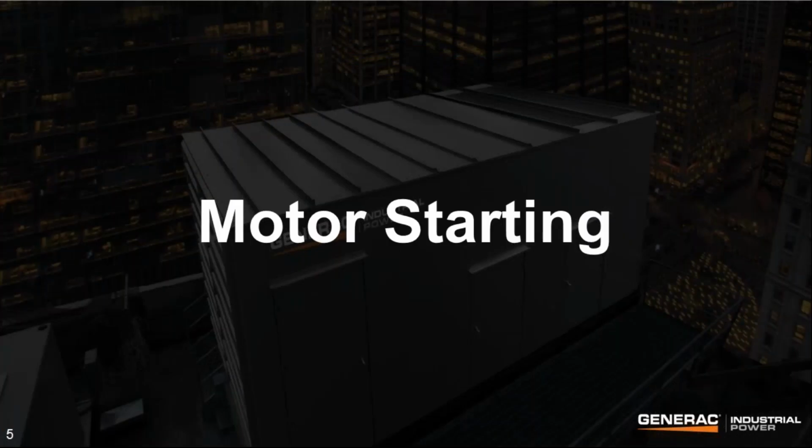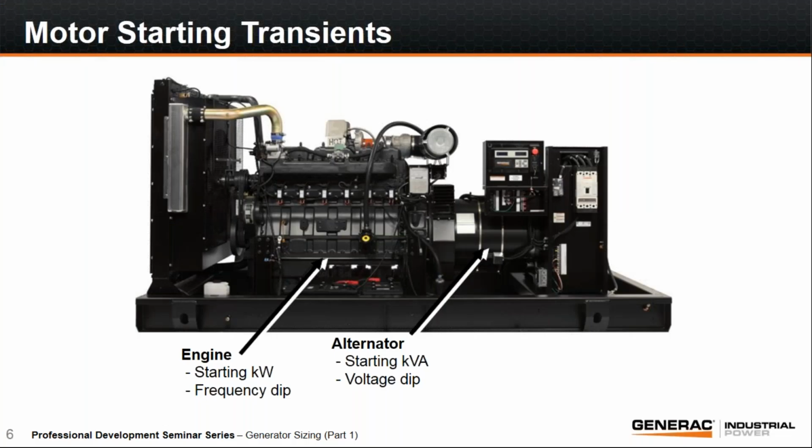Appreciate that. So let's chat about motor starting. We find with generators, one of the interesting aspects of applying a generator to a load is when we start a large motor. And when we start a large motor, it actually applies a transient condition to both the engine and the alternator on the genset. The alternator controls our voltage dip and our engine controls our frequency dip.